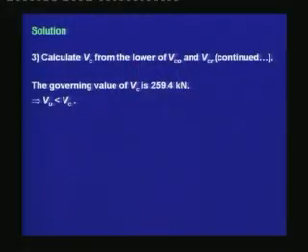This is a substantially high value because the second term in Vcr is substantially high. This means the shear corresponding to a moment that will generate a flexural crack at the critical section, which is at the face of the support, is extremely high. We do not expect to have a flexural crack near the face of the support, and hence in this particular situation, Vc is the lower of Vco and Vcr, and we select Vc is equal to 259.4 kilonewtons, which is the value of Vco.